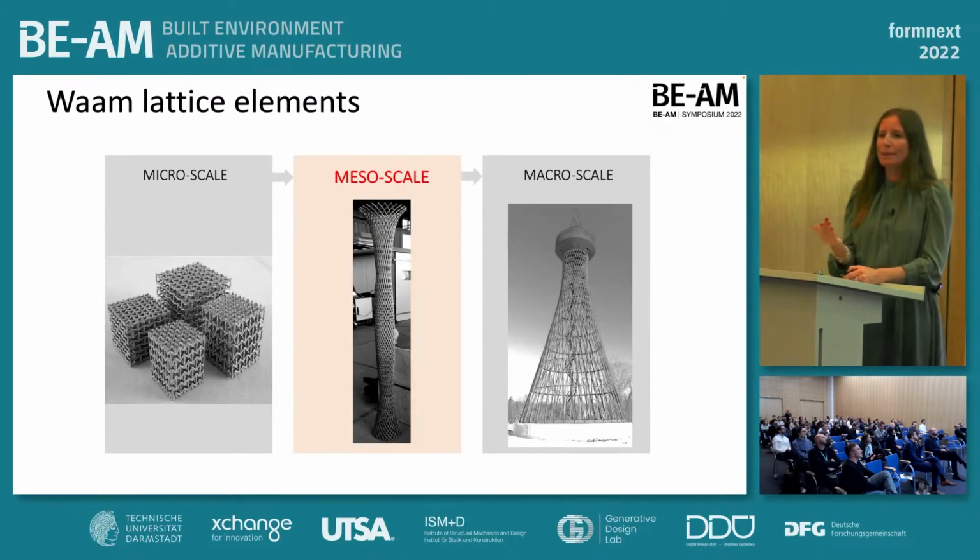Why lattice elements? Well, we all know that they are highly efficient. At the micro scale, so at the scale of the single material, lattice elements are well renowned for high stiffness and low material use. At the macro scale, as engineers, we all know about truss elements and truss systems, and these are again very good for high stiffness and low weight, so low material use again.